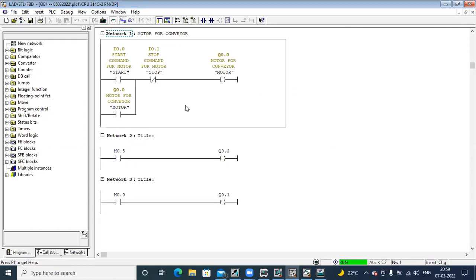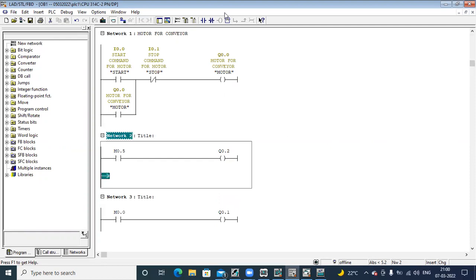So, for example, I want to know the status of the motor on a panel. We're having LEDs. For that LED, I want to flash, right? This motor Q0.0 is connected to a motor, okay, hardware. Whereas Q0.2 I will use for lamp indicator for showing the status of the motor, whether the motor is on or off. So for the flashing in parallel, means for one lamp I am having two conditions, either flash or steady continuously on.